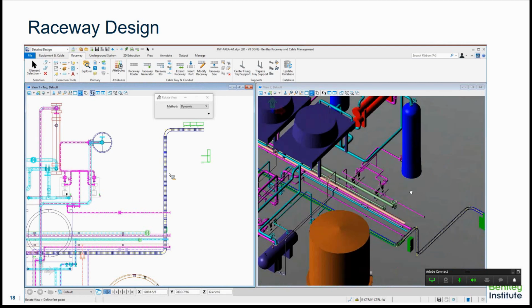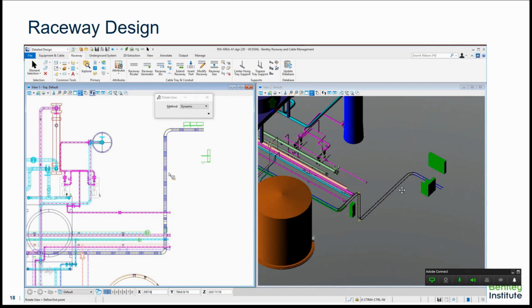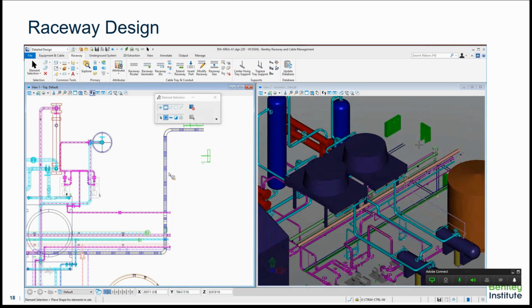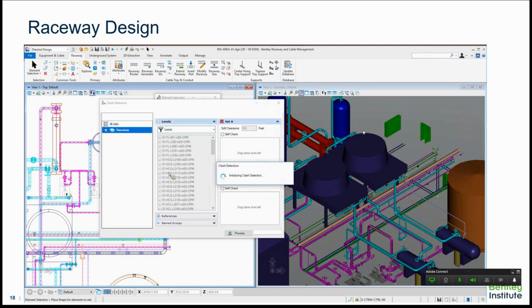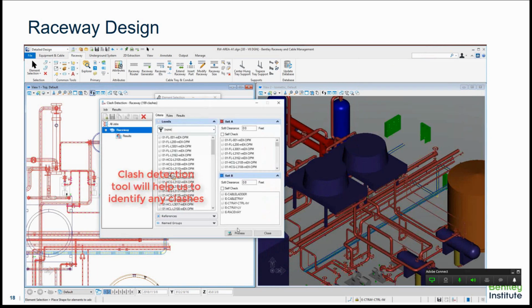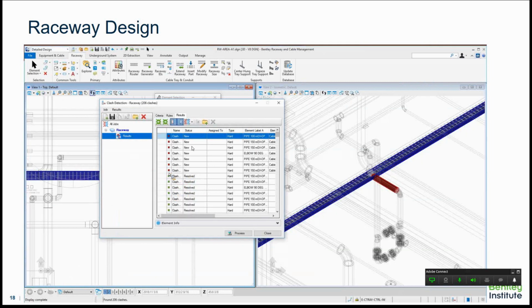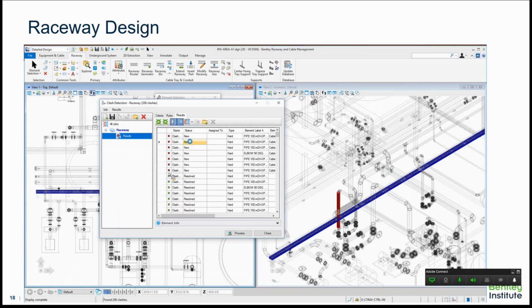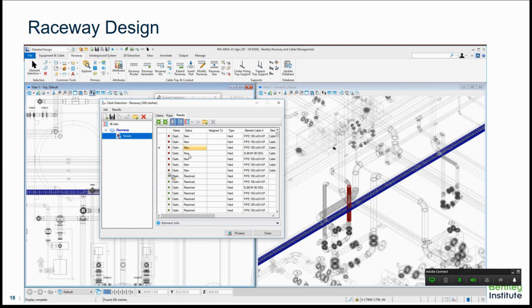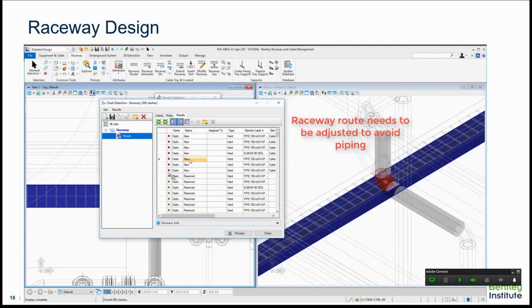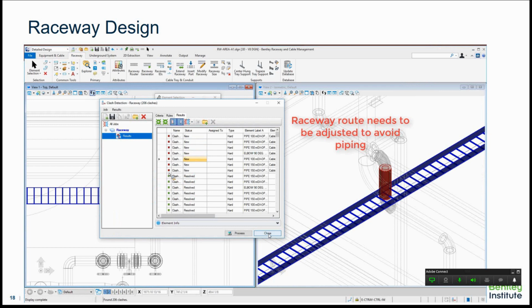So again, a lot depends on working with AccuDraw, so definitely you have to be familiar with MicroStation, with simply navigating and working in the MicroStation 3D environment and the AccuDraw. Notice that I wasn't really careful when I placed this Raceway, so guess what? There's a lot of problems with how I did this. So there's a lot of clashes. I ran this Raceway right through the piping, so definitely not a well-done design.